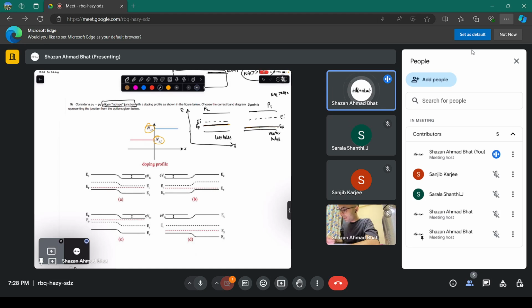that means electrons are going from this region to this region, and holes will come from this region to this region. Because for holes, everything that happens for the electron in this band diagram, the opposite happens for the holes. We draw this band diagram with respect to electron energy, not with respect to hole. For holes, we consider everything to be opposite.